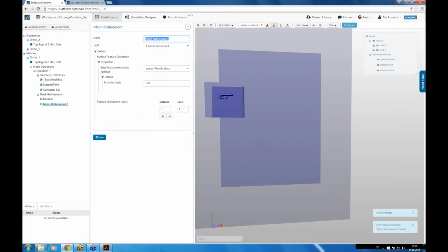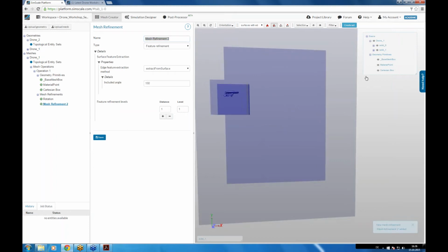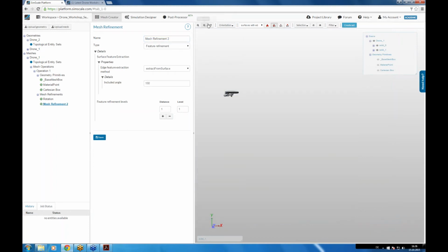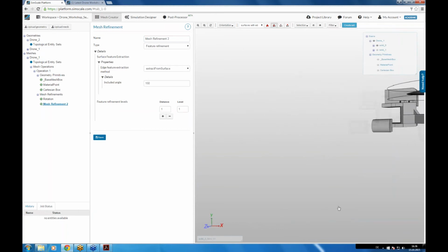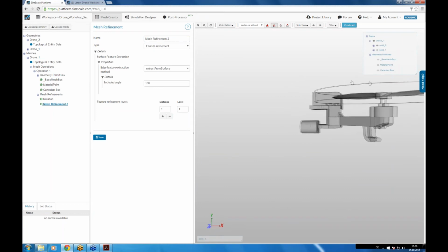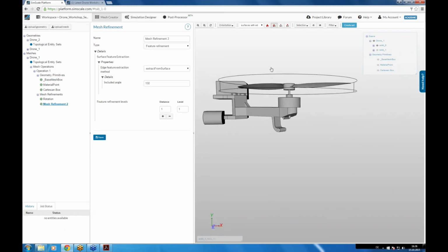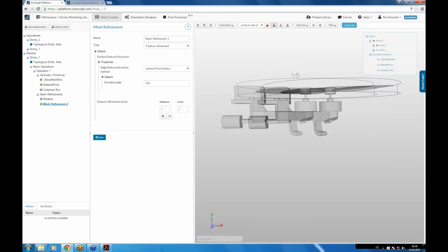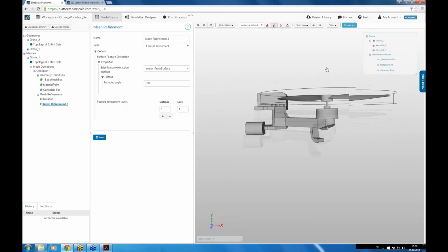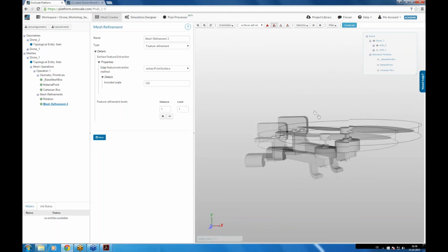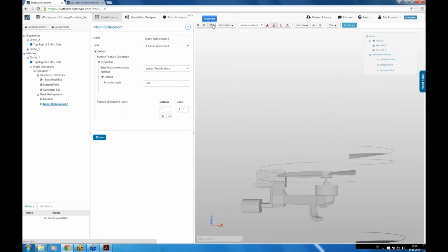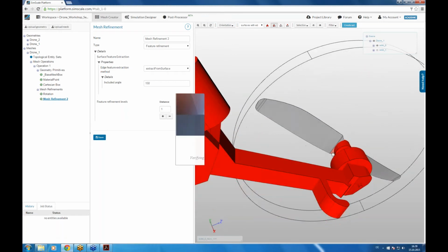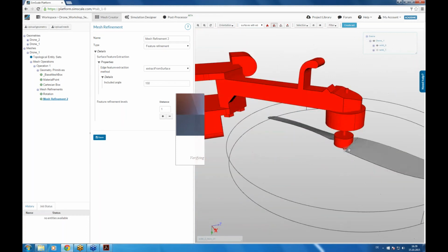Now we have to refine some of the surfaces. Therefore, let's hide all the boxes here and also hide this, and let's start with the refinement. By the way, you can interact with the model with your mouse, and if you want to change the center of rotation, just double click with the left mouse and then you can change it. And here, if it's necessary, you can reset the view. Okay, now in here you have to be very careful to select what you need.